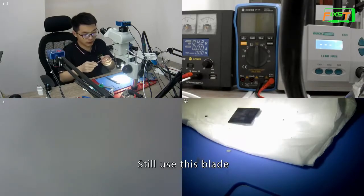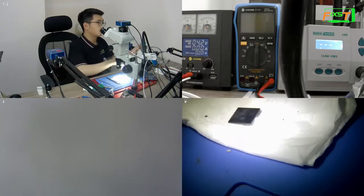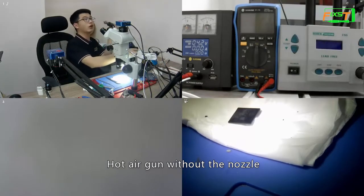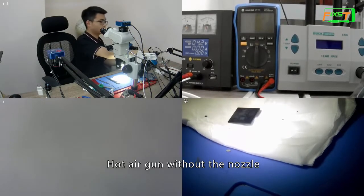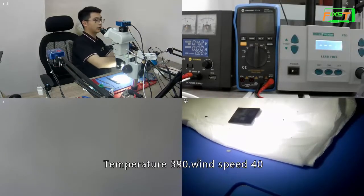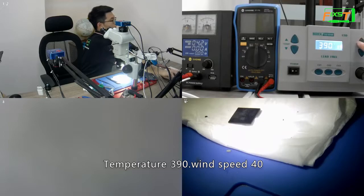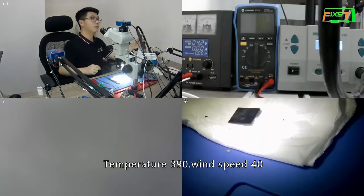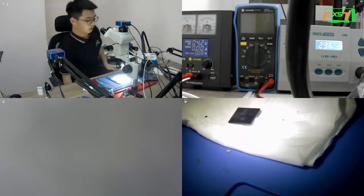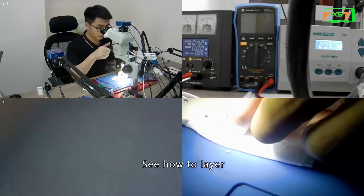Still use this blade. Hot air gun without the nozzle. Temperature 390, wind speed 40. See how to layer.